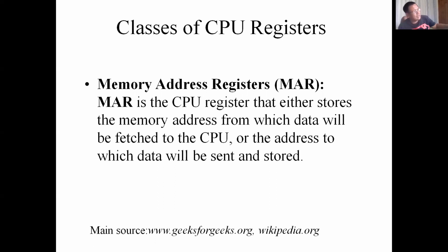Okay? The addresses are stored in the memory address register. We do not access the memory address register ourselves. We can only access the accumulator and the data register. The memory address register, we do not access it. It's the CPU that controls it. Do you follow?